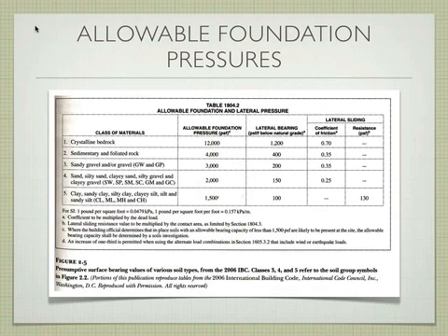Okay, so this is a table, I think out of your book, figure 2.5. Allowable foundation pressures. I'm not going to ask you to memorize any of this. This is the kind of thing that if you really need to know, you're going to look it up in a book. You don't need to know these specifically, but it gives you some idea. These are pounds per square foot of weight that this soil can support. 12,000 pounds per square foot is in bedrock, and we come all the way down to clay, and it's only 1,500 pounds per square foot. So that's a major difference when you're thinking about the weight of a building.